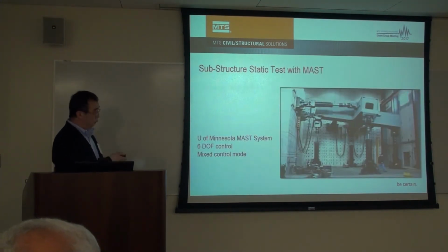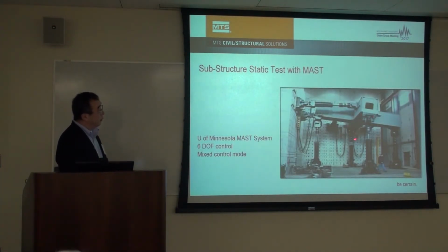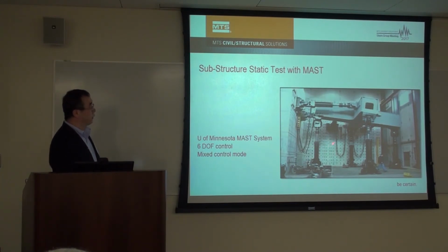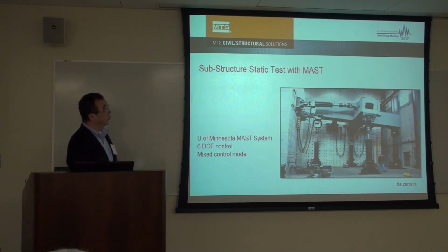For example, this master system with 8 loading actuators, we have a control algorithm to make sure that any point can be controlled in global degree of freedom, in any degree of freedom. So this is called the degree of freedom control.